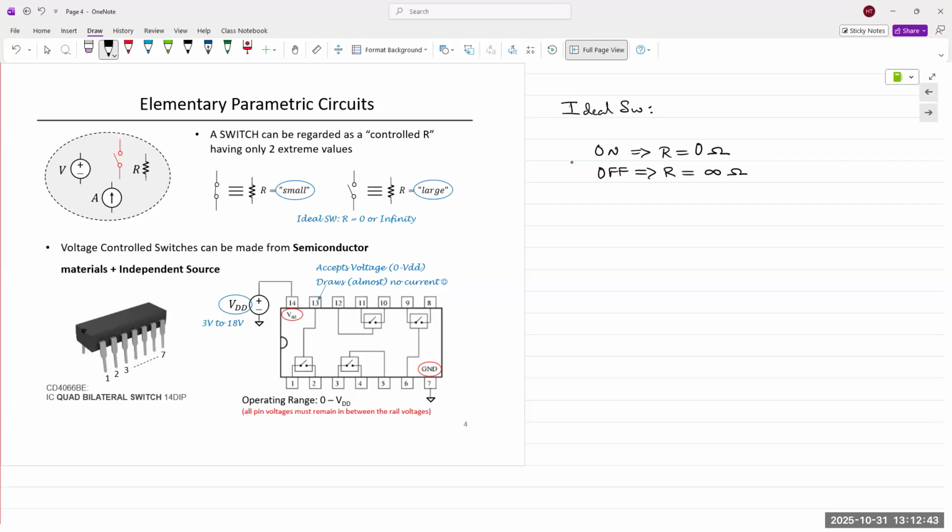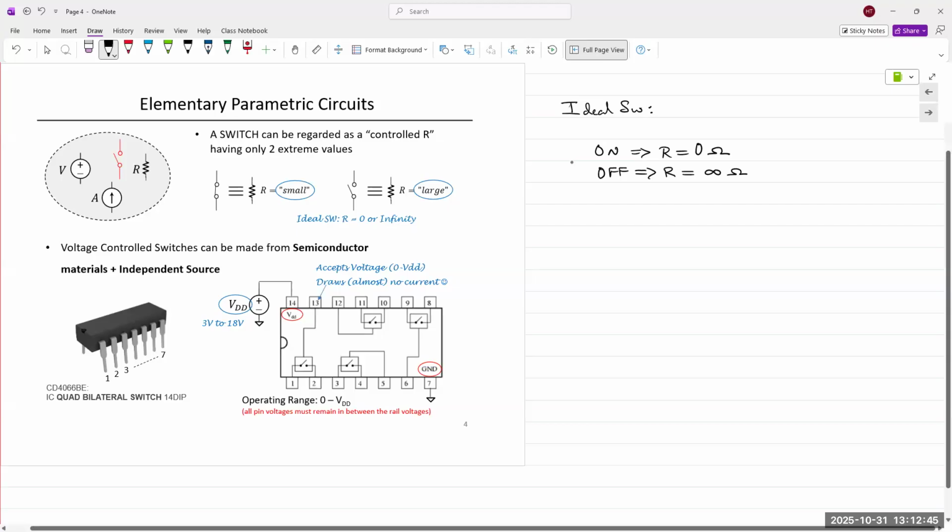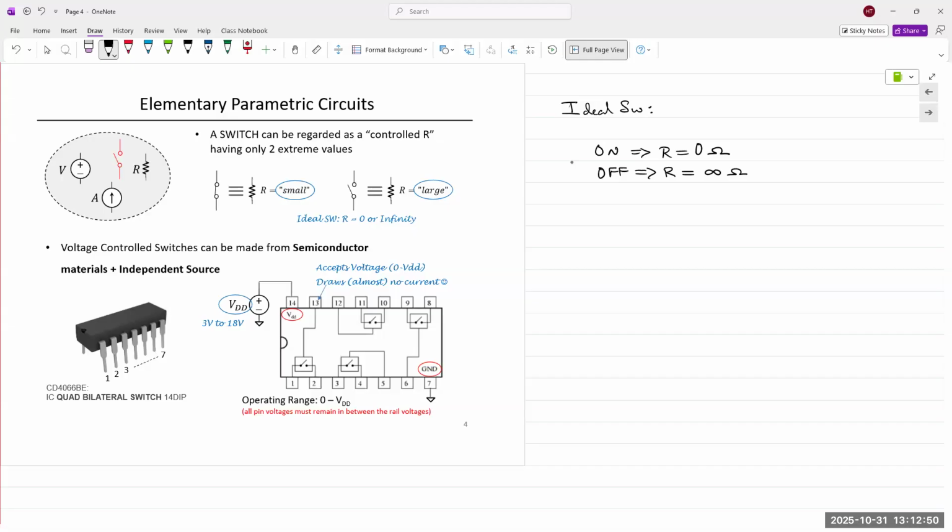Now that's the design part of it. That's the binary math part of it. When it comes to the circuits part of it, it still is voltage and current. So a typical digital system, let's say it goes from 0 to 5 volts. If it's logic 0, it means it's 0 volts and 0 current, ideally.